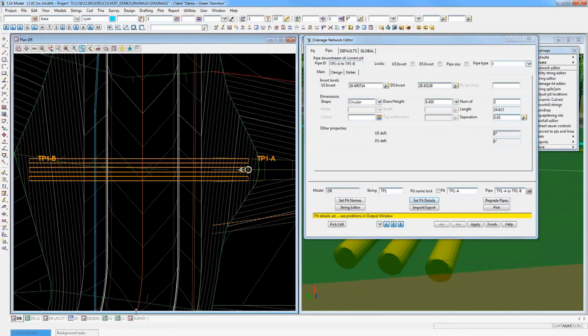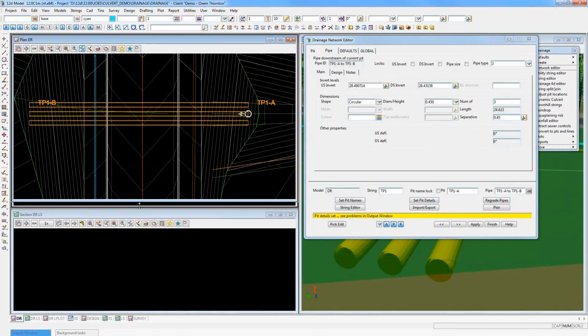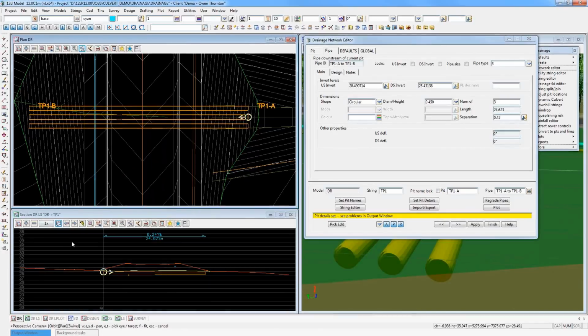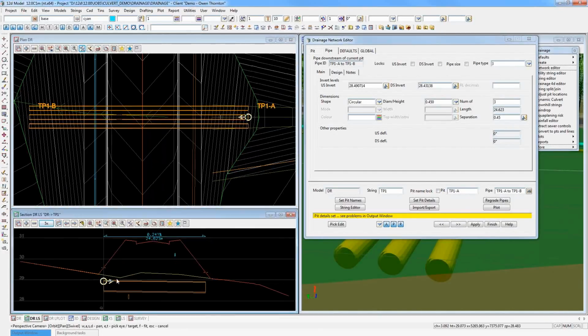Okay, so that's got the basic shape of my culvert in place, but let's now have a look at it in section view. I'm just going to drag my plan view up here, and I've got a view prepared below, a drainage long section view, it's called, and I'm just going to profile that new culvert that I've just designed. And if I make that exaggerated at about 5 times, say, you can see initially when you lay down a culvert in 12D, it normally makes the culvert too deep because it's trying to maintain your specified pipe cover limit across the whole length of the culvert. And a culvert, or in fact any drainage string that's supposed to daylight or stick out of the ground, is supposed to breach its cover limit at certain points. Otherwise it can't stick out of the ground.